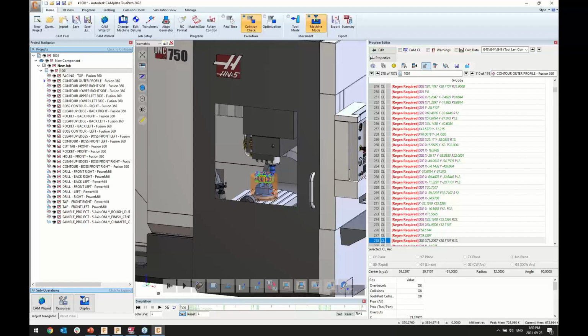Yes, so NXCAM, it's not a full-on plugin that will export the models. The models themselves will have to manually be exported, which again is not too much of a heavy lift. It's simply export in STL, IGES. Specifically for the actual toolpath information and tooling, we are basically piggybacking on the CLS file format that has been enhanced on our end. So there is a custom CLS format that we would provide that at that point has been extended to pass additional information for the tooling, the holder shape, and so on. So yes, there is a similar way to pass that.